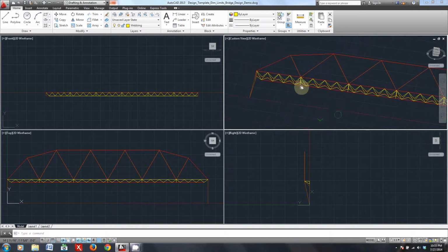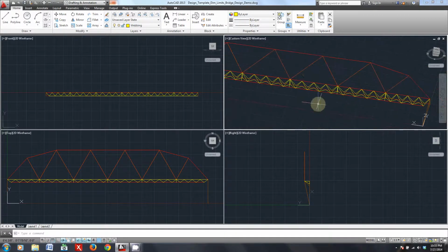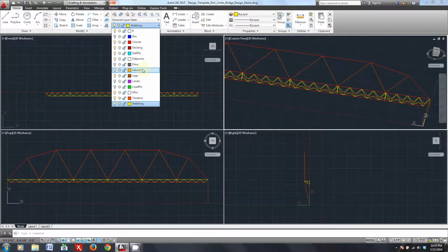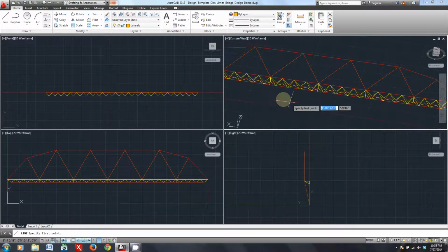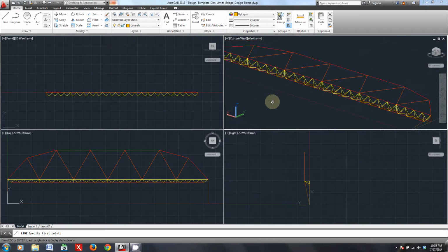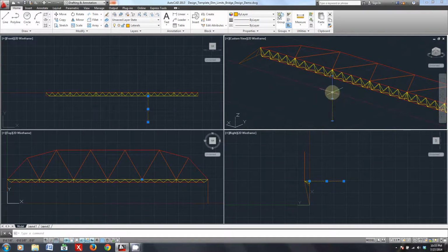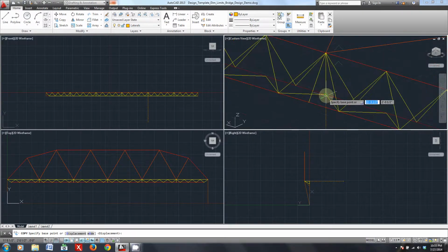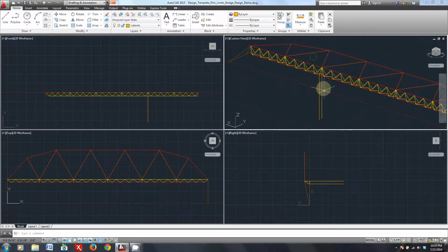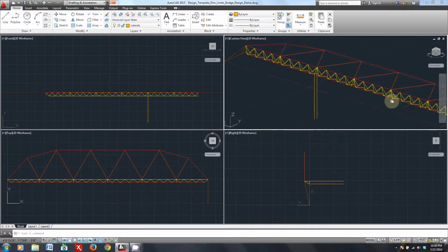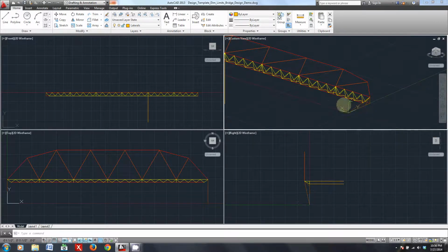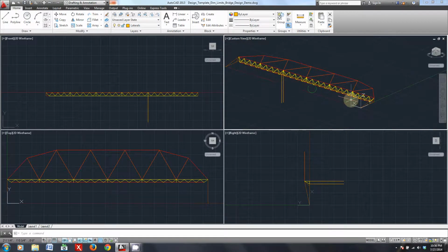So now, how do I tackle doing, say, my laterals? Well, in a similar fashion, you can go to your laterals layer, and I'm going to construct one of these very simple laterals here, starting from right there, and say it's 2 foot, maybe 11 inches. Sounds like a good number. You can copy that down, and you can do the same kind of webbing thing in here. By the same process, you can flesh out your other laterals throughout the rest of the bridge.